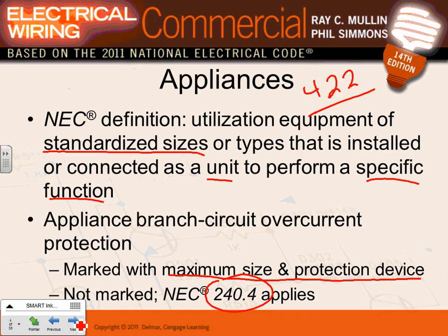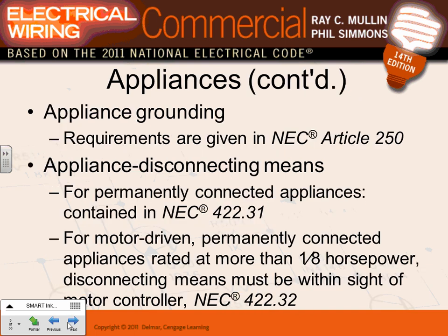If you remember, 13.3 amps or less, 20 amps, more than that, we use 1.5 times the size of the protection device. But almost always the appliances, guys, that you have in a commercial industrial application are going to have what? The nameplate on it that says what the overcurrent protection device is, what the conductor size is, what the amps are, what the voltage is, and you have to provide a disconnect for it. So that's really the most part of it.